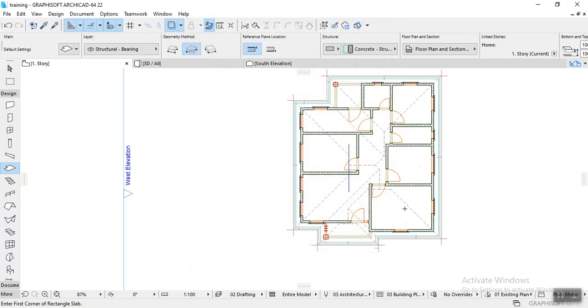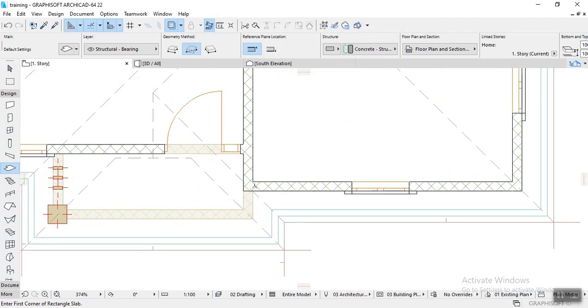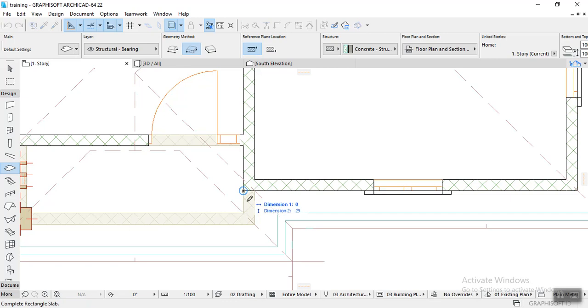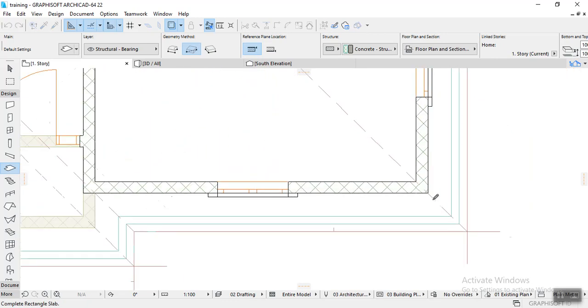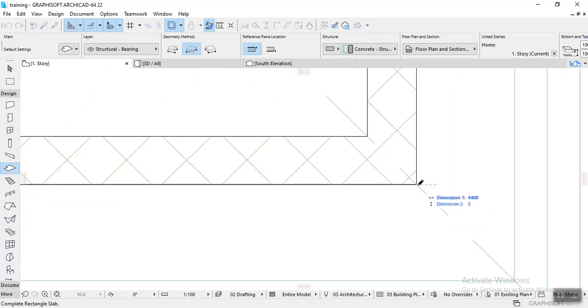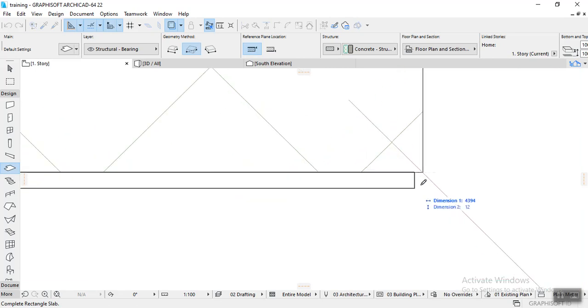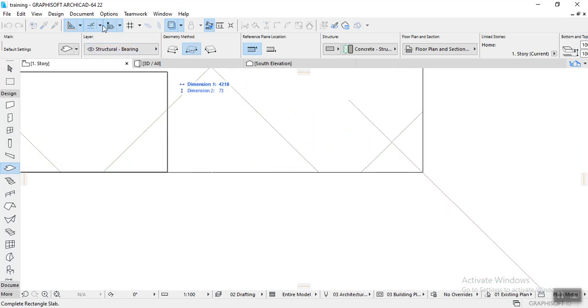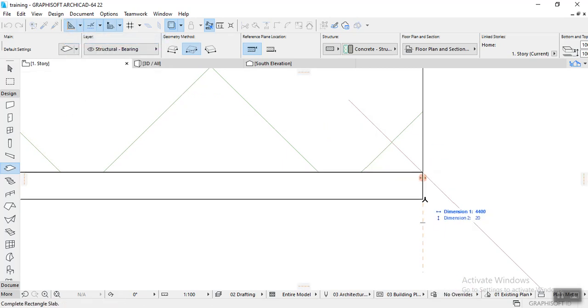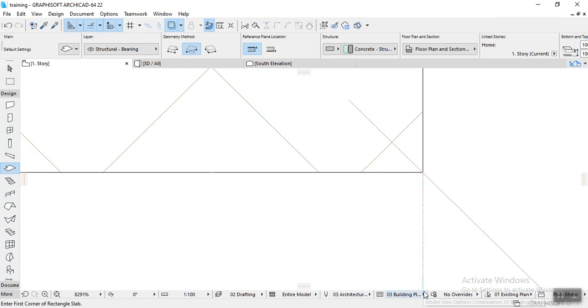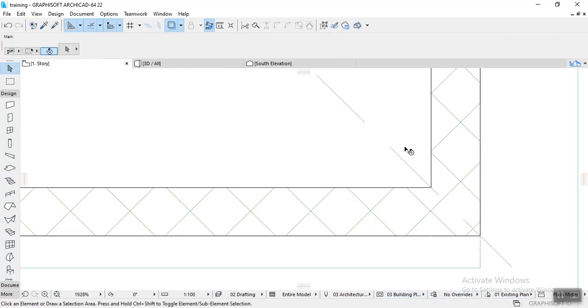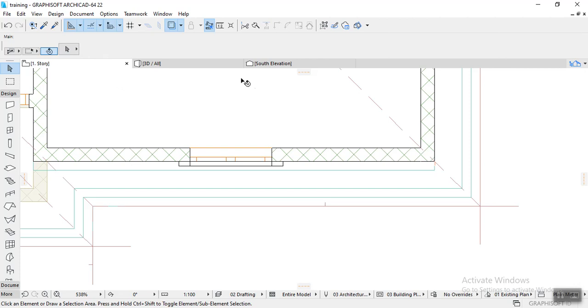Okay, so I'll click, then I'll come down to this spot, I'll put a wall here. I need a guide. I'll pick a guideline, I'll create it here, then place this. I want this to be 100 as well. Okay, let's see what we just did on 3D.